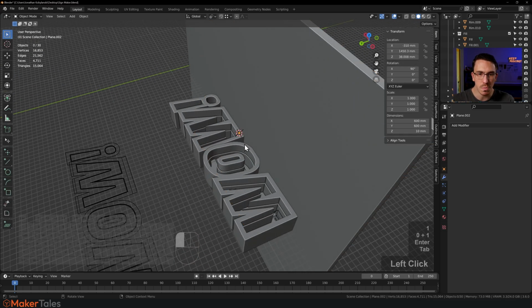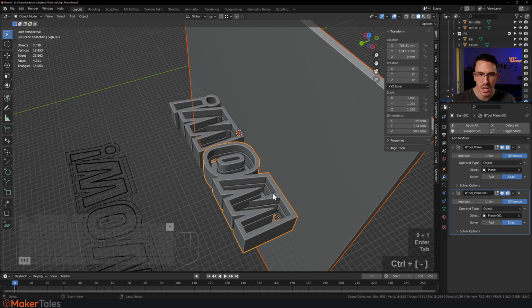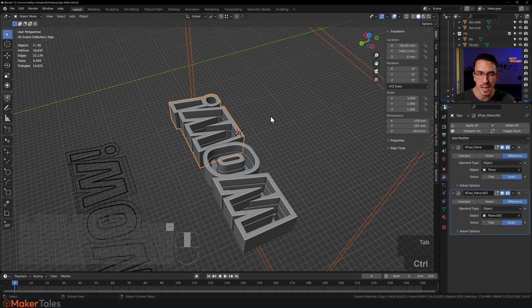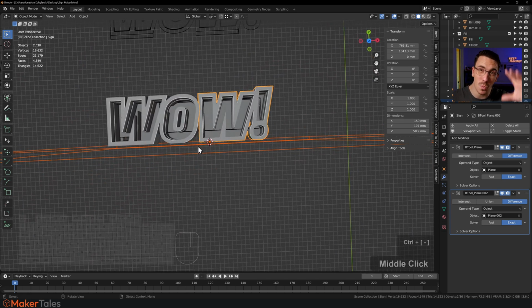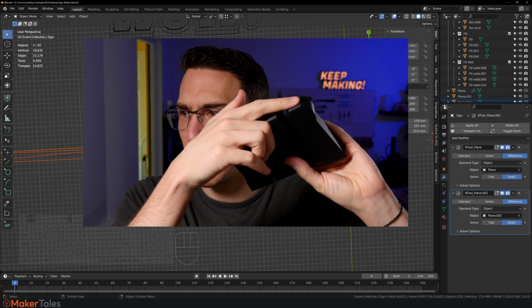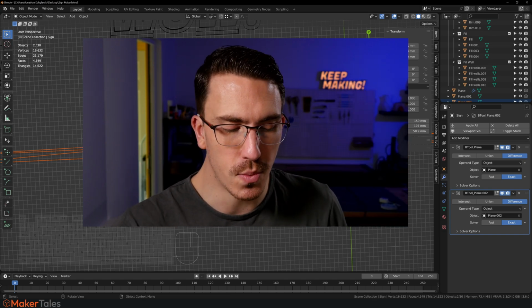And then I'm going to do a bool tool cut to the bottom of both of these, so this is perfectly flat and I can put this wall down on a surface. And in fact, that is what I've done down on here. Let me just show you. On the bottom of this, you'll see that it is flat. It's because I did this trim operation with it.